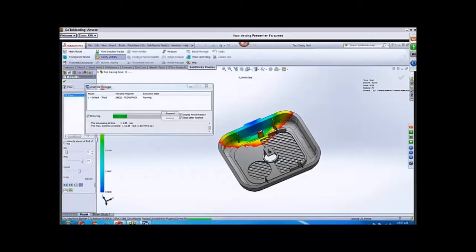So this is filling in plastic with time, and one of the key advantages of this is that you can see the plastic fill up, and if there is a problem of some sort, you can actually stop the analysis in the middle. You can go back and make a change as necessary. And already I can see that there are a few problems. Take a look at these ribs right here where my mouse is.